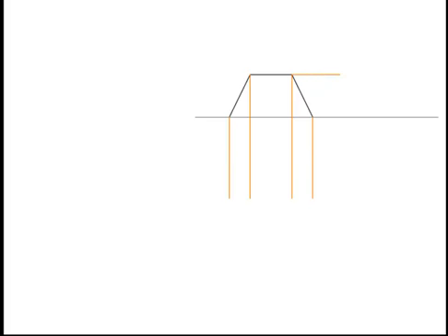First of all, we begin by drawing an XY line. Now we draw our piece in elevation. Now we project down our lines from elevation to plan and also across to the end view. Now we can draw in our plan. We will draw a 45-degree construction line which will help rotate our points in plan up to end view.